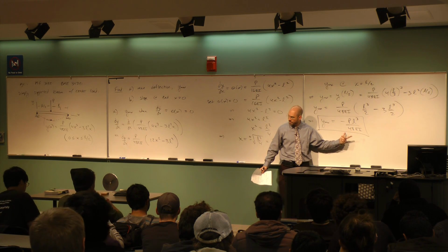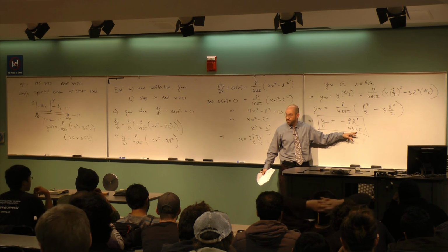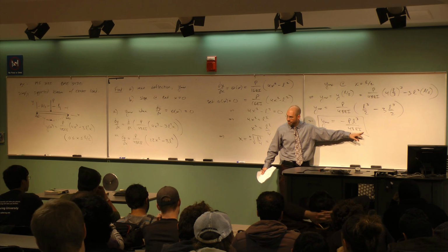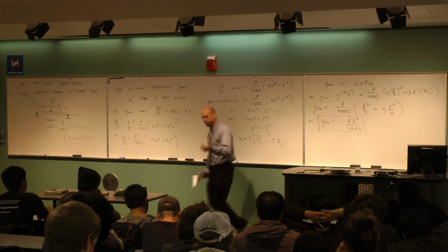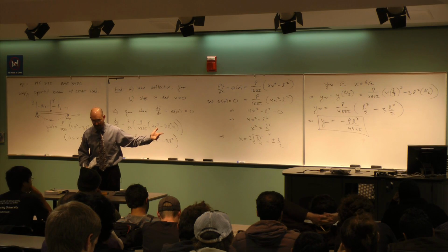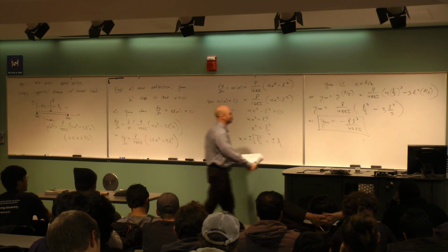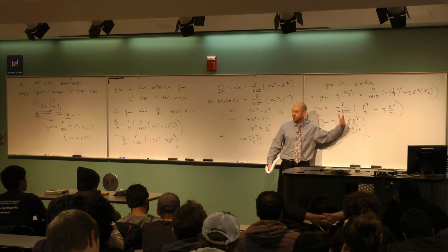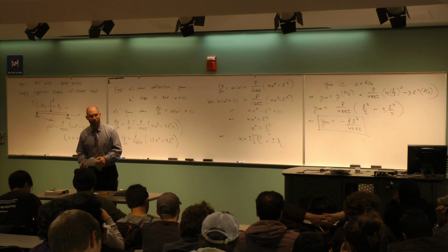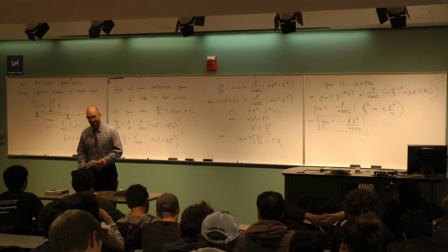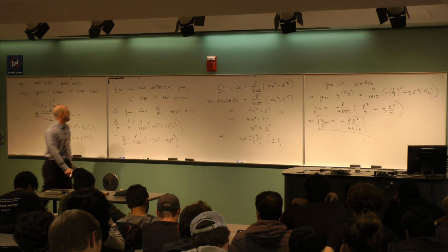If I put numbers in, for example P in pounds and L in inches and E in PSI, pounds per square inch, and I in inches to the fourth, if you do the math on all those units, you're going to get out just inches when you're done. If I were in SI, I would put in newtons for pounds, meters for the length, pascals, newtons per square meter, for the E, and then meters to the fourth for the I. And when I did all of that, I'd end up with just meters at the end. The beauty of these problems is, if it's all letters, then you can't screw up the units. The units are built into the letters. It's a good thing. All right, so next question. What's the slope at the end x equals 0?